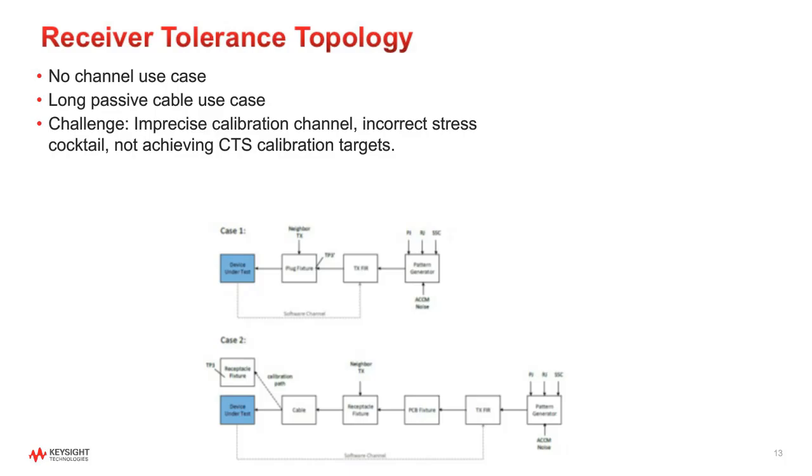So the answer is there's no LTSSM software option because there's no need to go through the link training state to get into the test mode. The only time you worry about link training would be in the bullet that says sideband decode. That's when the live link is being used, but it's not required for compliance testing. So another great, tough question from Aurelio.